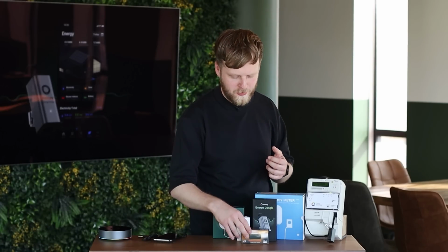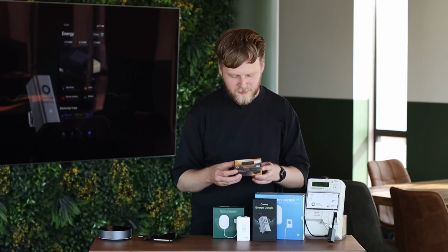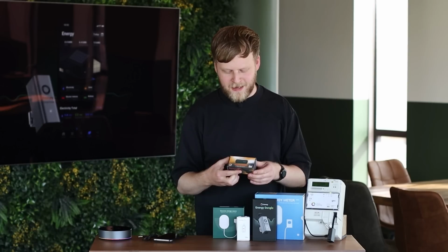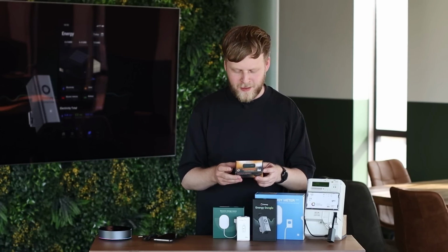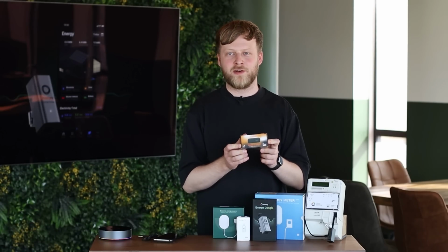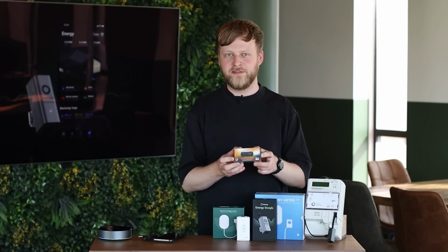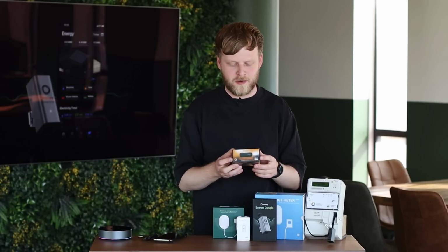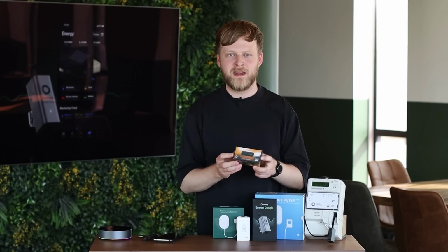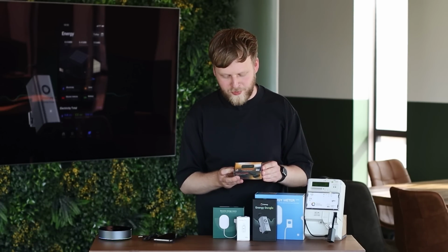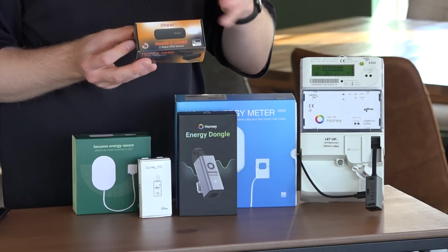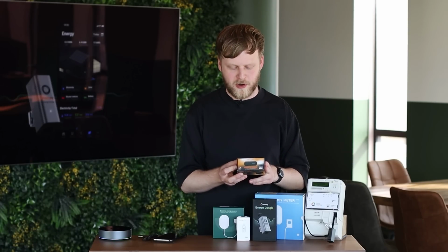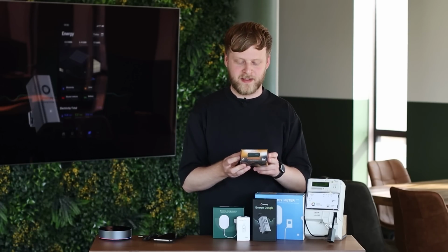One of the other options that you'll see, especially in Norway, is the HAN standard. It could be a bit confusing, since HAN is used in different ways, and sometimes it also says HAN P1. But usually the HAN standard you find in Norway comes with an RJ45 jack, so a full-sized Ethernet jack you could compare it to. In most meters in Norway you can connect, for example, this Heatit Z-Wave ZHAN2 and get all your energy data from your HAN-enabled smart meter into Homey over Z-Wave in this case.